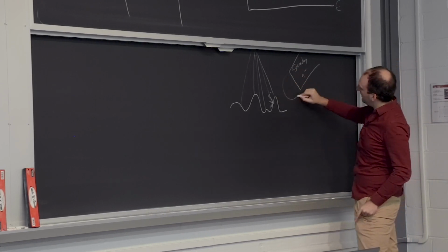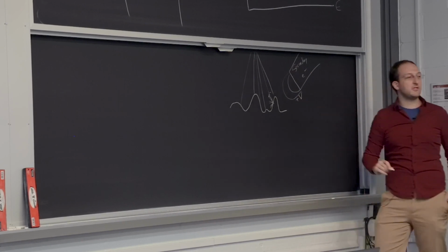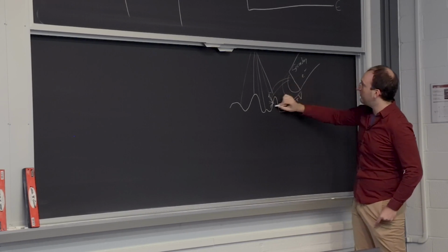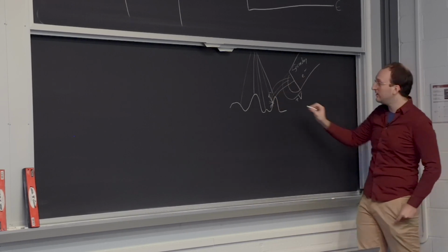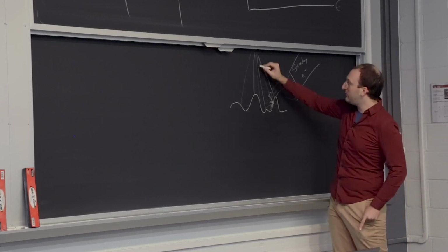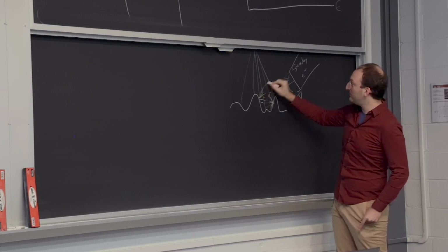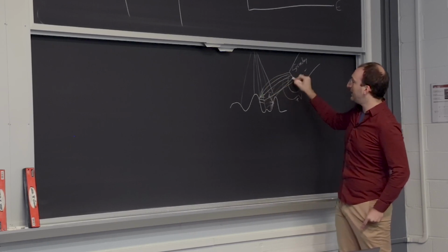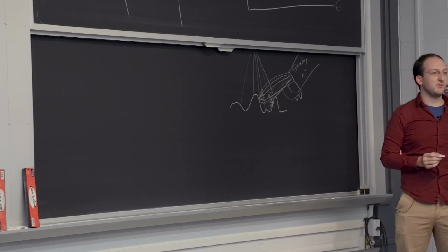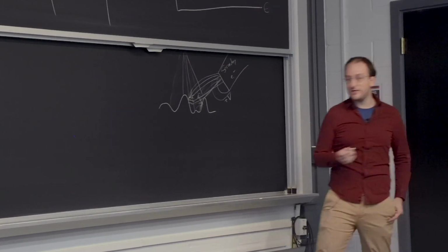There'll usually be a little cage with some sort of a positive voltage on it to attract those secondary electrons, and some of them will curve into the detector and become part of your signal, but some of them won't. Meanwhile, if you have this beam right here producing secondary electrons, pretty much all of them go slamming into your detector. And that's what actually allows the electron microscope to get topology. That's why images in the SEM look fairly 3D.